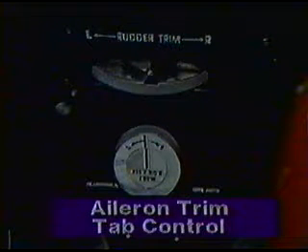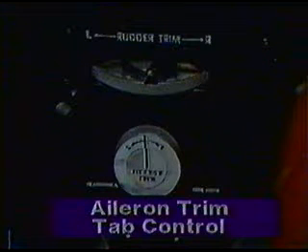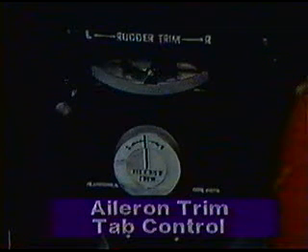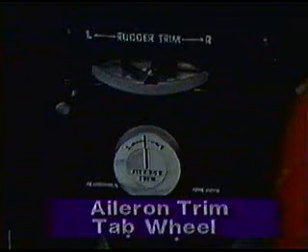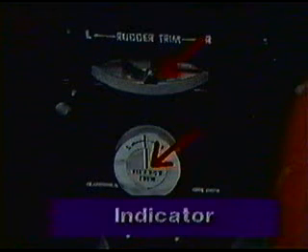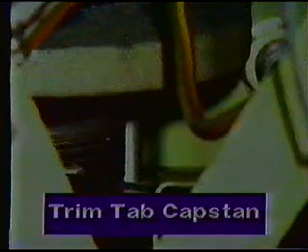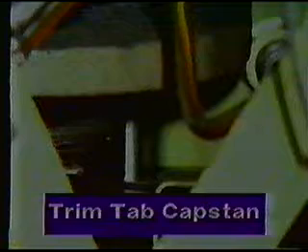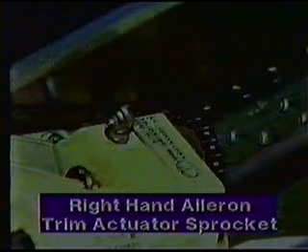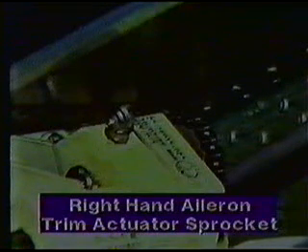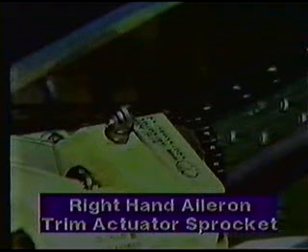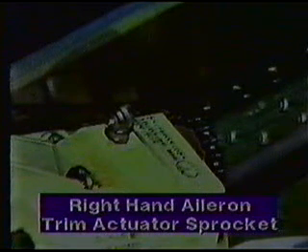Components of the trim tab system include controls installed in the pedestal identified by the tab they control, such as aileron trim tab control or aileron trim tab wheel. The center of the control that shows the tab position is the indicator. The unit that is rotated by turning the trim tab control is the trim tab capstan. Chains and sprockets used in the system are usually referred to by the tab involved, such as right-hand aileron trim actuator sprocket.